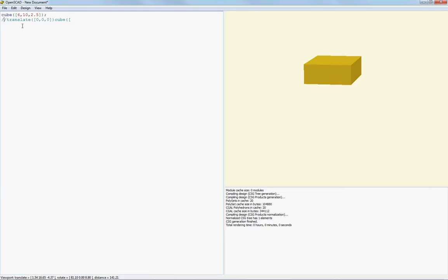We're going to bring this back in. To comment out, you just put // and it comments it out, and it doesn't get compiled and is ignored. Kind of useful if you're just trying to do some experimentation to see how everything works. So we're actually going to have 0, 0, 2.5. We know that's going to be the height.